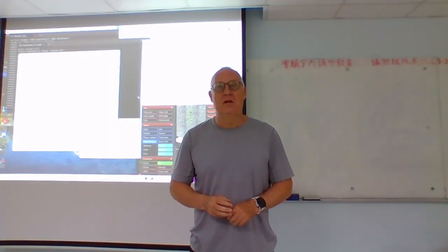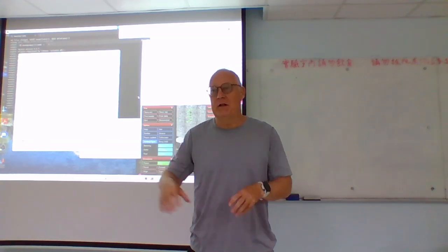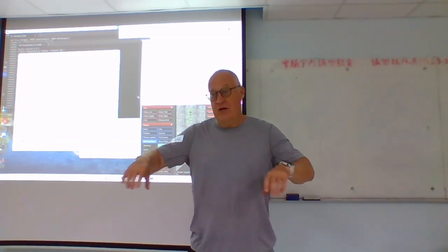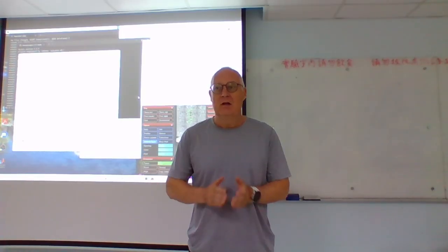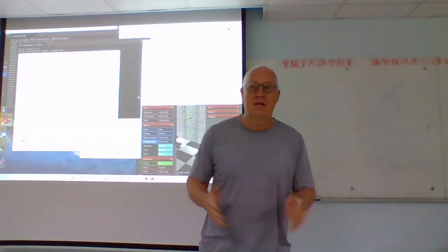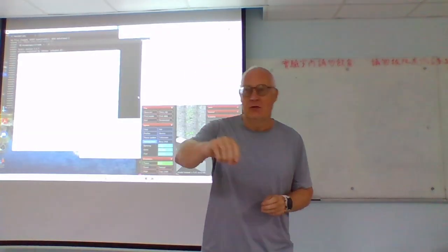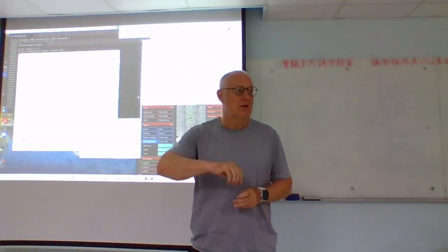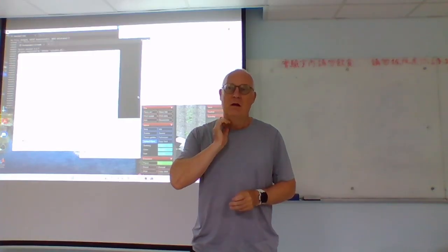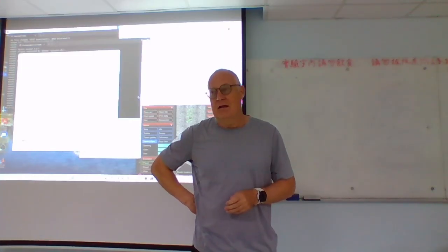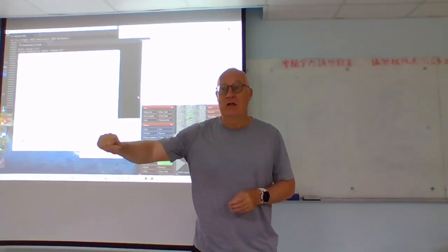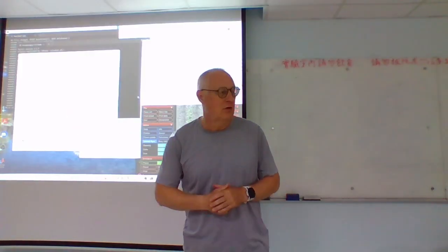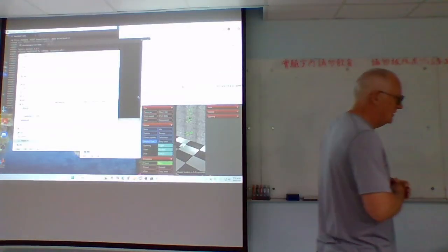In some industrial robots, like a Cartesian robot, where you just have two linear actuators, X and Y, and it moves like a plotter, the kinematics are very easy. You just go to X location and Y location and it moves in a straight line. But anything with revolute joints, where you need to do rotation and convert it into motion, you need to understand the kinematics.